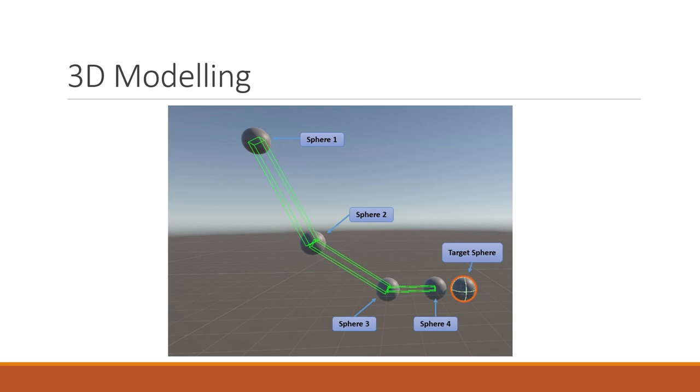It will move on Y axis from 0 to 190 degree with a counterclockwise movement. Sphere 3 will act as the wrist of the humanoid robot, where it moves on X and Y axis and from 0 to 190 degree with a counterclockwise movement. Sphere 4 will be the end effector. It will point the endpoint and it will act as index finger on the humanoid robot.